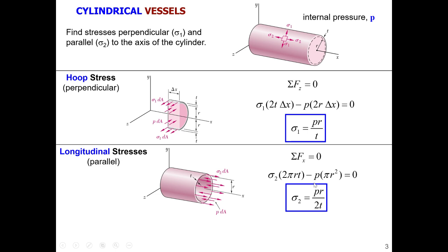And in fact, what we can see now is that the formula for the hoop stress and longitudinal stress is very similar. The only thing is that we have that factor 2. So the hoop stresses obviously will be larger as we apply P and compare it to the longitudinal stresses in direction x and 2. Okay. All right. So with this, what we also can do is look into the situation. This is for normal stresses, but do we know anything about shear stresses here? So in fact, we can calculate what is called maximum shear stress, right? So that is doable. We can do that.